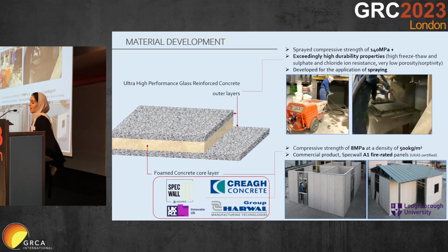And again, by increasing the strength, we've done this strategically so that we can reduce the thickness of the outer layers of the panel that we need. By reducing the thickness, we're able to maintain the lightweight aspects of the sandwich panel, which is what it initially has. And obviously with that, because we are using UHPC, we get very high durability properties.